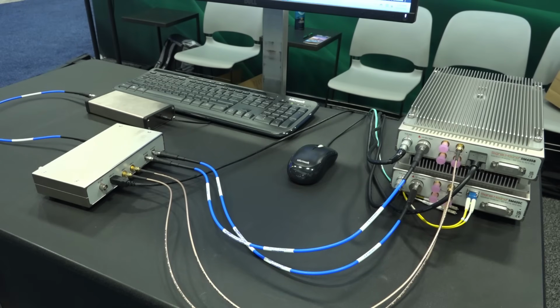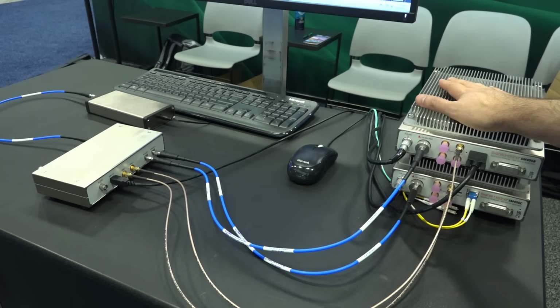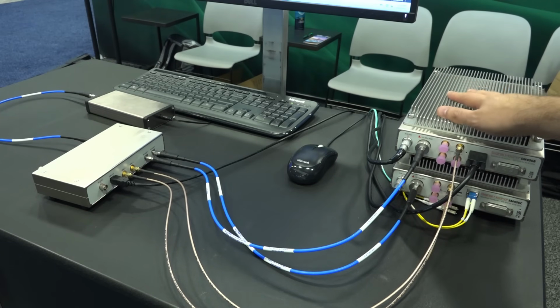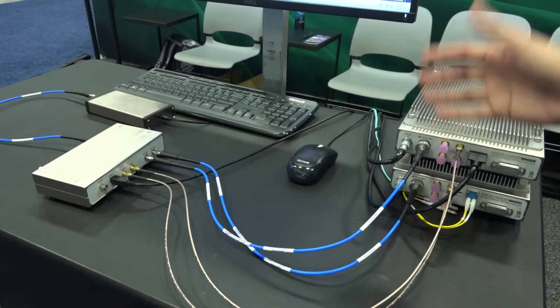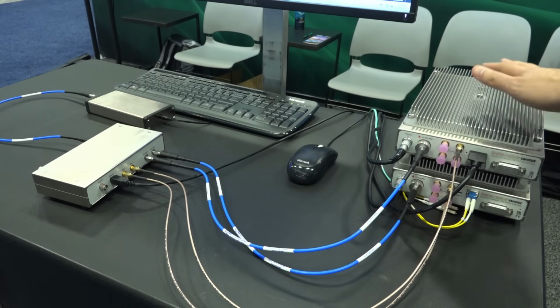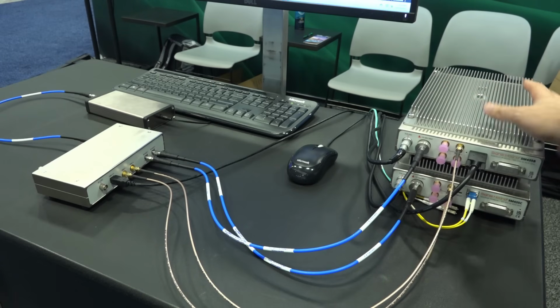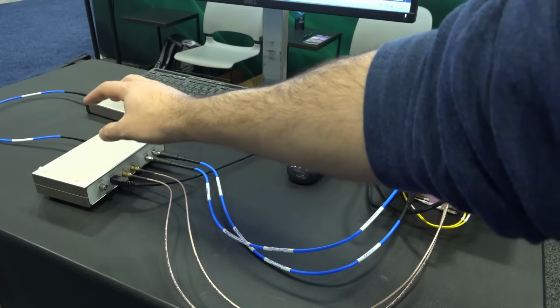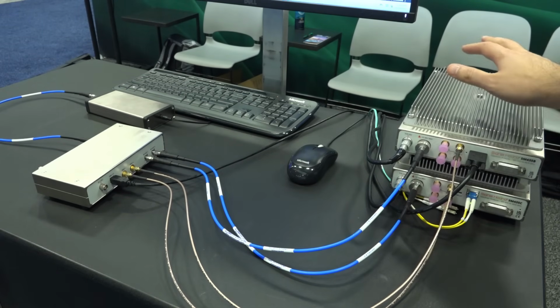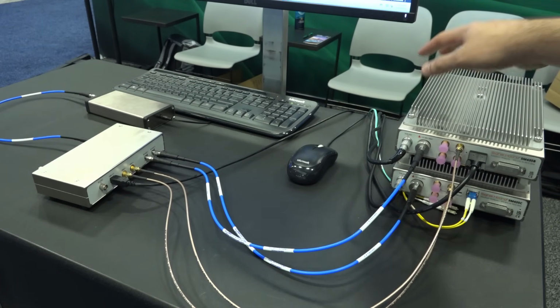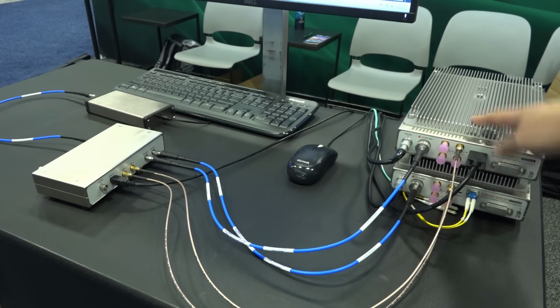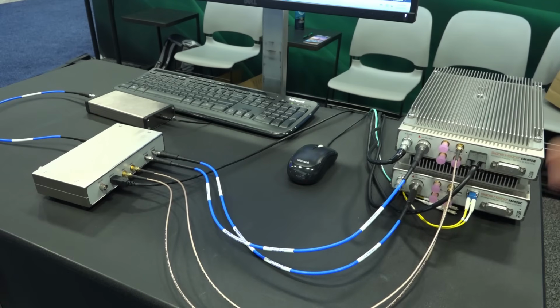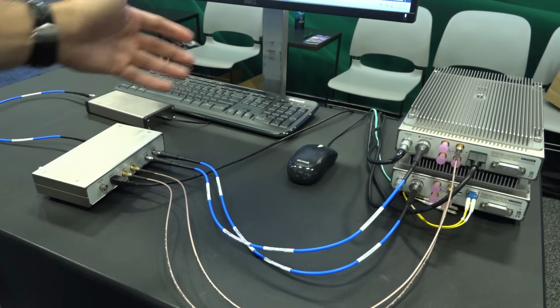So here we have the phase noise analyzer, and one of the advantages of having multiple copies of these real-time analyzers is that the theory for phase noise analysis is cross-correlation. Because these are completely independent synthesizers and completely independent LO architectures, if you get your signal and feed it into this box that does the appropriate division between the two of them, and you have software running, you can do a cross-correlation phase noise measurement. In fact, they can go down to almost minus 180 dBc of phase noise measurement through the correlation techniques over here.